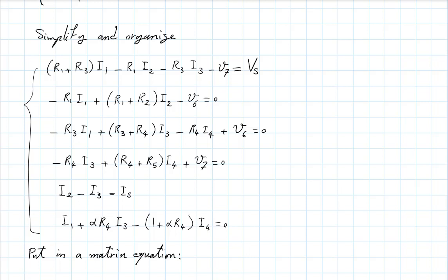If you have 10 elements in parallel connected between two nodes, with nodal analysis one node would be the reference and the other would give you one KCL that gives you the node voltage. If you wanted mesh analysis, you would have 9 meshes, a 9 by 9 matrix.